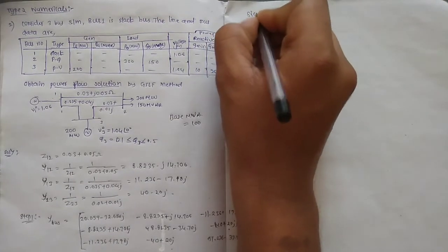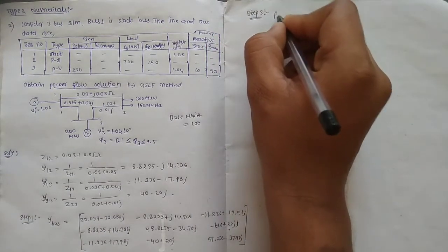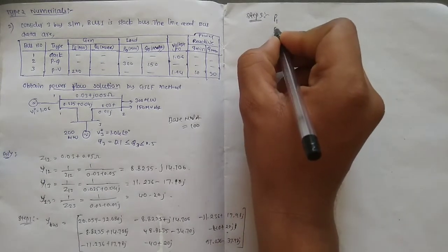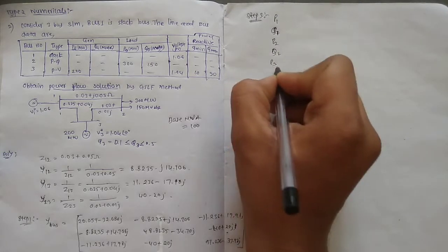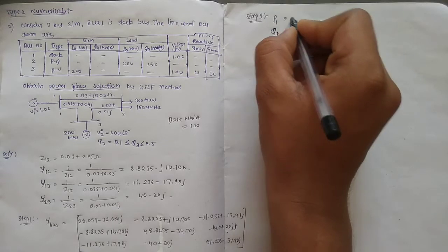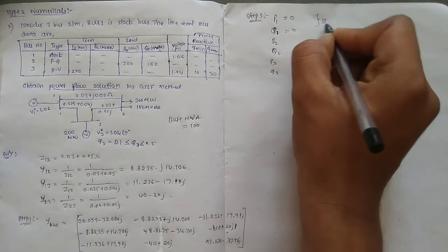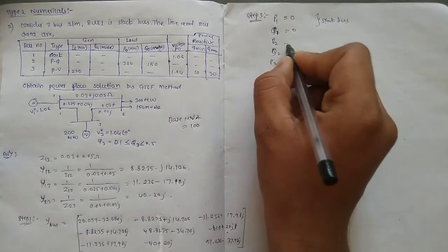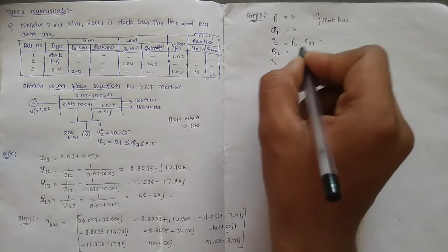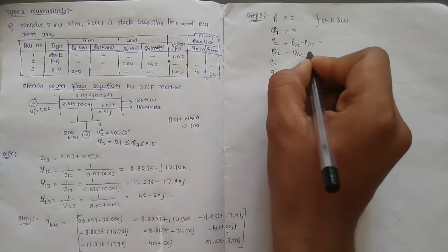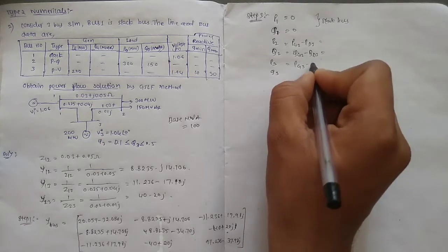Now the third step is for P1, Q1, P2, Q2, P3, Q3; we need to calculate all these parameters. Since P1 is equal to 0 and Q1 is equal to 0 because of the slack bus, and P2 is equal to PG2 minus PD2, Q2 is QG2 minus QD2, and similarly for bus 3,